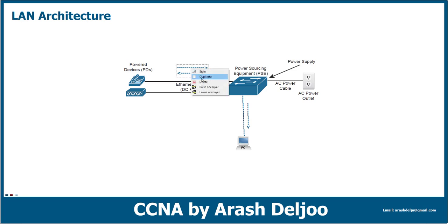Because of that, first we have a negotiation between these two devices. If the negotiation result is that this is a PD, a powered device, you can apply the power to that device. The question is how the switch can negotiate with the other side. Let me emphasize that this is related to level 1 signaling. But also, with the auto negotiation features of the Ethernet interfaces, we can talk about the PoE capability with the other device.